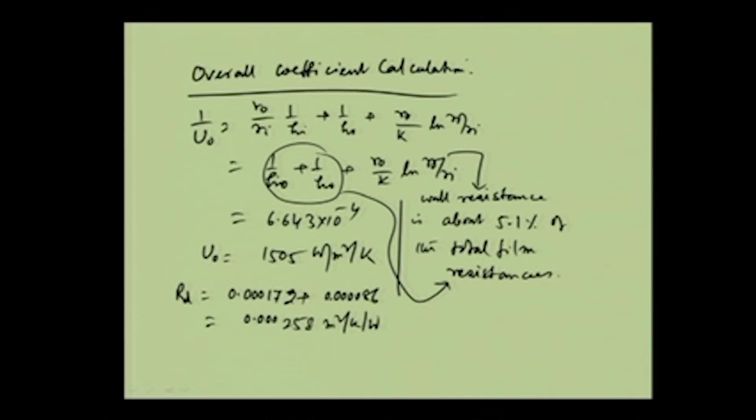So one side fluid is the water side, and the other is benzene. Okay, so we will take something like that, and then UD you will get from the relationship of this, and UD we can find out as 1084 watt per meter square per Kelvin. Now once I know UD, then we can find out the area based on the outside diameter.